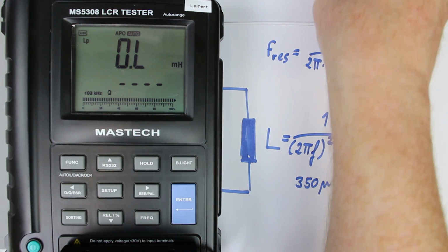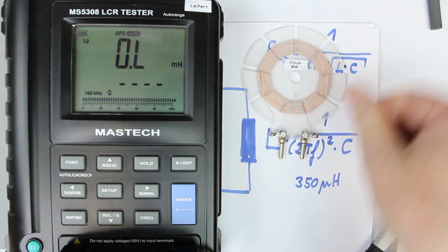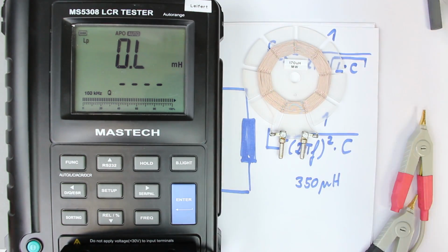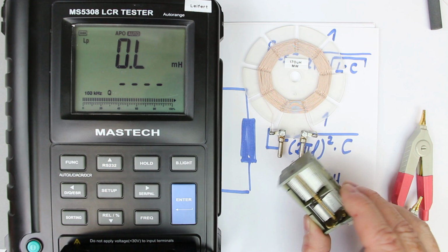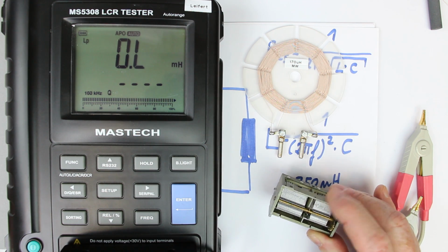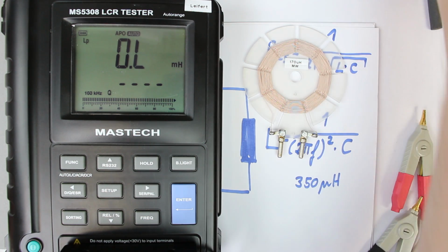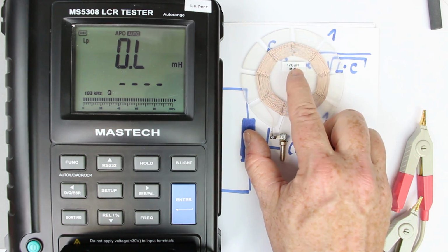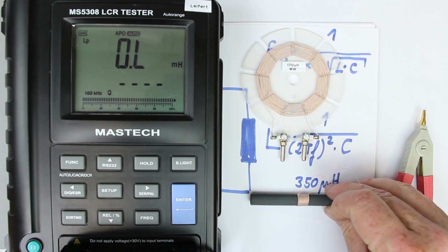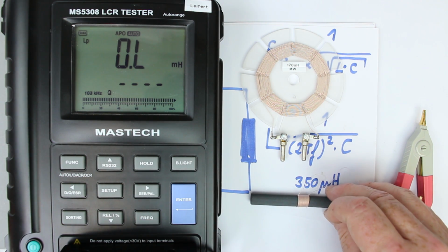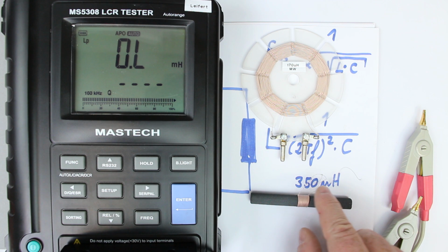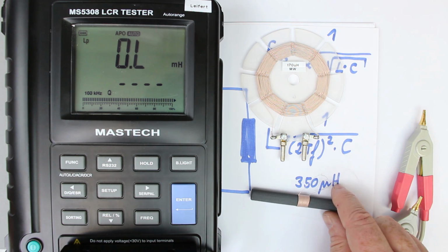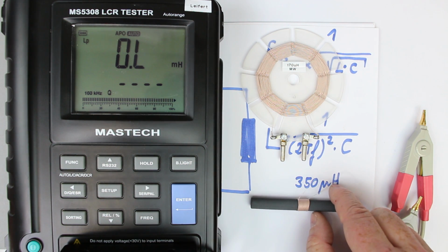And the same, I wound this coil for this kind of rotary capacitor, and it also has around 600 picofarad. And that's the reason why these AM antenna coils have a somewhat lower inductivity than what's calculated for a 290 picofarad.